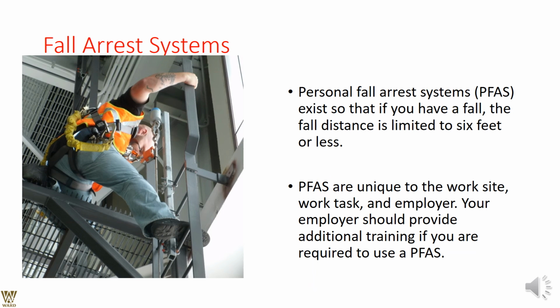accident that comes. So, personal fall arrest system, PFAS, that I've been talking to you about in the previous slide. The person you look at is completely fastened around here on his body. It protects the person from falling to the ground, no matter from which height. Yes, to a certain degree, there will be jerks on the body. Yes, definitely. And if it is ergonomically suited, it in all probabilities will not harm even your internal organs. Remember, personal fall arrest systems are unique to the work site, unique to the task, and definitely your employer must embrace it